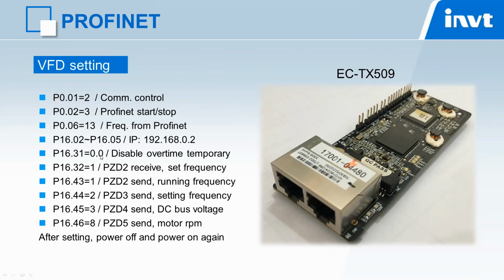P16.31 equals 0.0. This is the Profinet communication timeout time. In some software versions, the default value is 1 second. So if we do not set 0, after we insert the card and power on the inverter, the inverter will display the Profinet communication error. So we can set 0 temporarily. After all the network is working well, then we can set this.